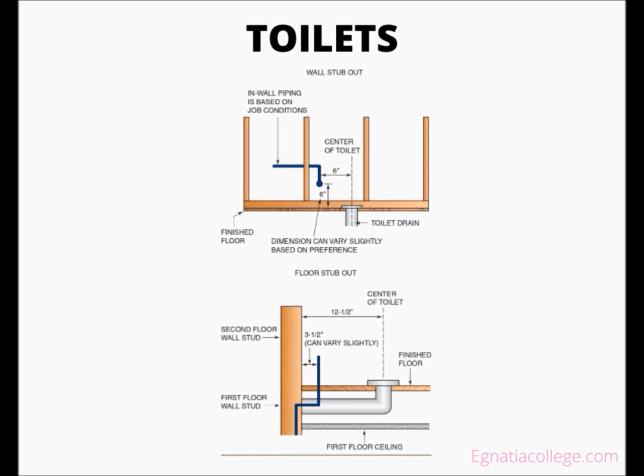If the floor is being tiled, the plumber must install the water piping higher to accommodate the tile. The wood trim known as base molding is higher in many custom homes than spec homes. If the plumber installs the stub-out too low, the piping conflicts with the base molding. If the stub-out is too high, making the final connection to the toilet may be impossible.